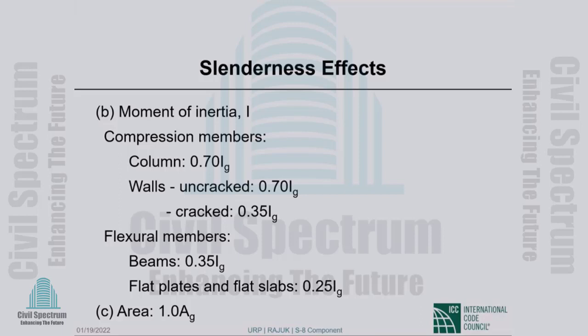However, we need stiffnesses for any structural analysis that we may want to do. And we always have to do structural analysis. Okay, we have wind acting on our building. We have earthquake forces acting on our building. How do we know the bending moment, shear forces in the structural members? By doing structural analysis. That requires stiffness assumptions. We have to assume the stiffnesses of the members.